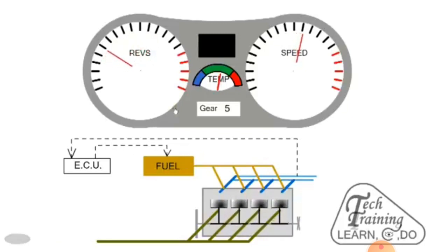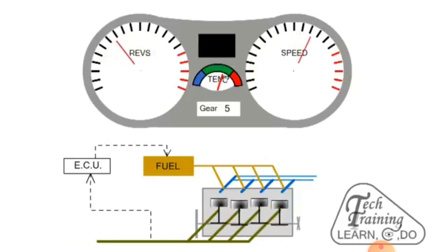When the engine is up to temperature and cruising, the ECU will use the feedback from the exhaust oxygen sensor to determine optimum fuel injection, thus reducing emissions and fuel consumption. This is called closed loop control.